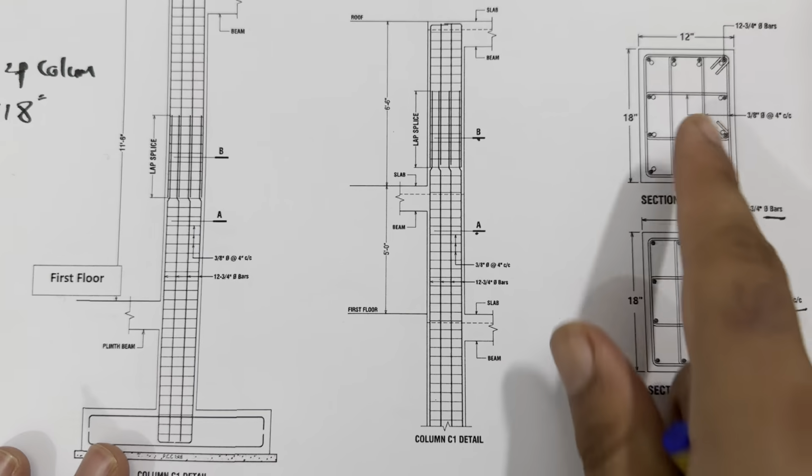You can see this is 5 feet, because here we have the beam, the first floor, and also you can see this is the beam, 6 feet here. So the total depth is, you can see our height is 11 feet and 6 inches. This is column details. On the other side, guys, you can see this is the other section. You can see clearly, as I discussed before. So if you are working on a construction site, this video can help you about the steel reinforcement and its size. This is especially for a 4-story commercial building.